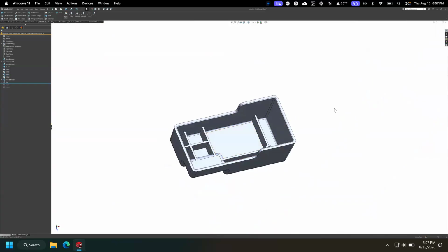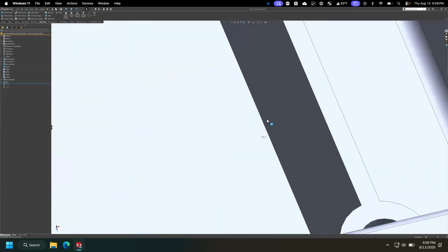Sometimes you'll add a feature to the injection molded part that seems perfectly reasonable, but it's a pain to machine on the actual tool because you have the inverse geometry on your tool, and it may be a feature that's very hard to machine that looks simple on this side, but isn't. So a radius on this side is a boss on the other.